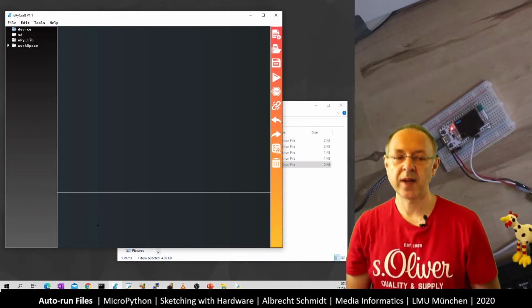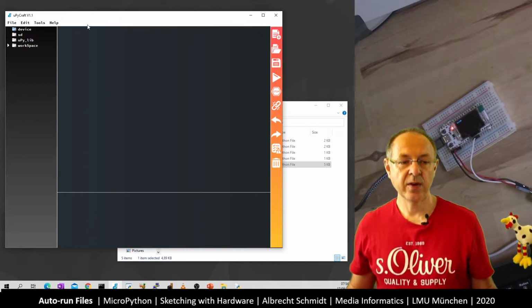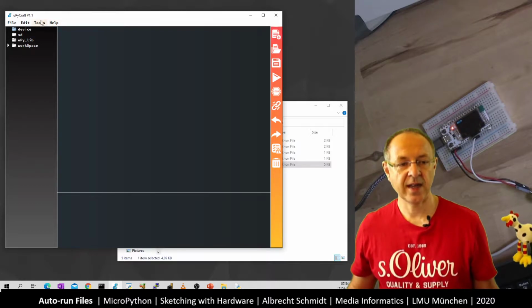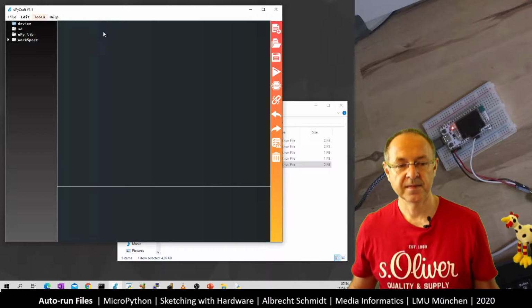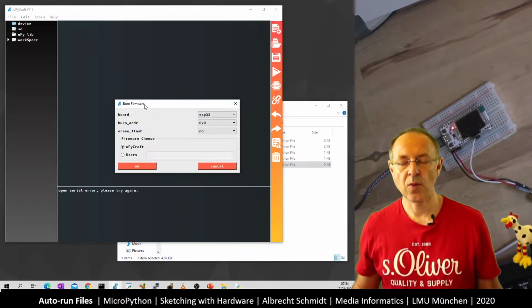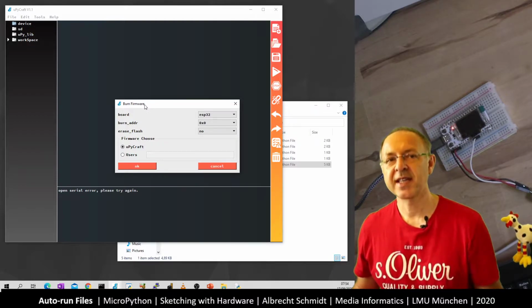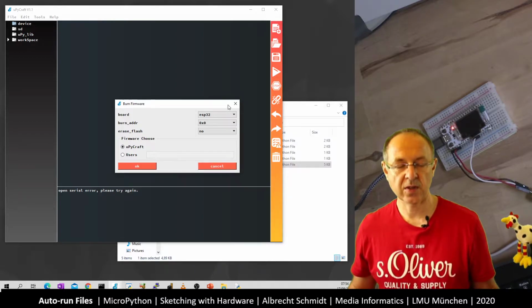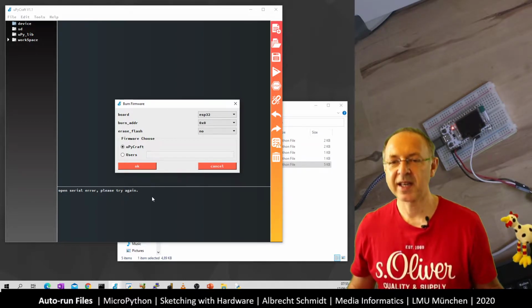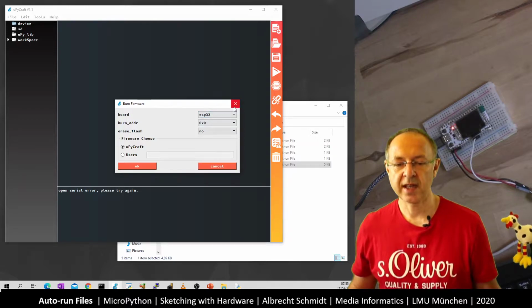As you see, it's running, but now here we are not connected. And if I try with the IDE to connect, it's COM4, something strange happens. So I get this, oh, burn firmware. And this is because it cannot connect to it. We don't want to burn the firmware because it's still on the file system, it's still there. So the problem is we don't get to the chip anymore. So what can we do?